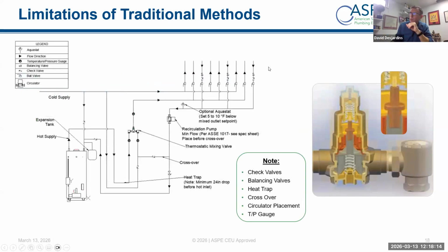From an installation perspective, I like going through this. Again, this is common for a mechanical valve, a more traditional valve. You have to think about it in two conditions. First, design flow: I have hot and cold coming in and a bunch of fixtures, which knocks the water temperature down. The opposite situation happens when I have no fixtures flowing. I have to get cooler and hotter water back here.